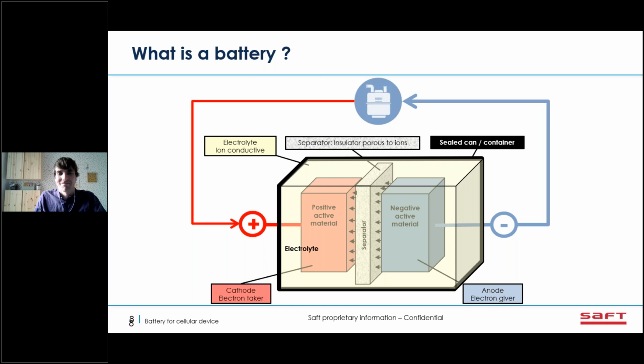Thanks, Isabel. There's another question. What is the best battery type for use at -30 degrees with 100 milliamp transmit and a minimum voltage of 3.3 volts? At -30 with a minimum voltage of 3.3 volts and 100 milliamps, clearly it will not be a battery alone. It will not be one cell. It's not possible. Perhaps some lithium-ion chemistries can do this alone, but not primary chemistries.